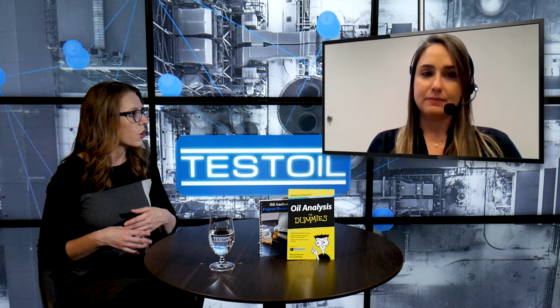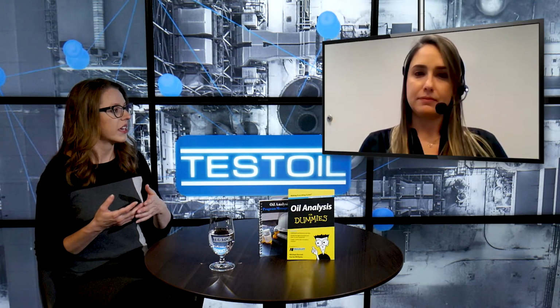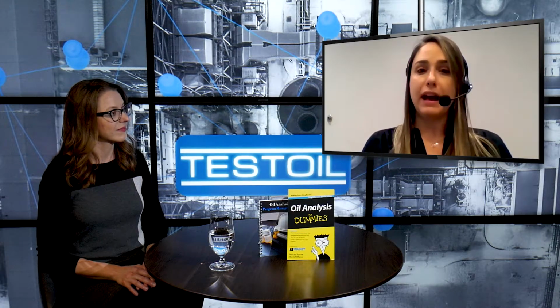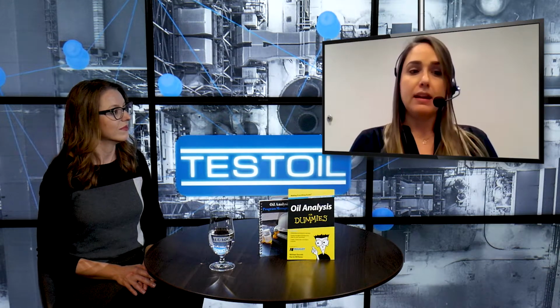Okay, that makes sense. So when you talk about the three forms of moisture, dissolved, emulsified, and free water, is there one of those forms that you feel is more of an issue than the other? So in a lubricating system, the two most harmful phases are free and emulsified water. Water will have a degrading effect on both lubricant and equipment. In the equipment, rust can be formed from the corroded components. It can even result in a chemical reaction with some additives through a process known as hydrolysis.